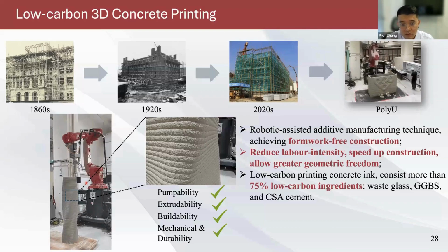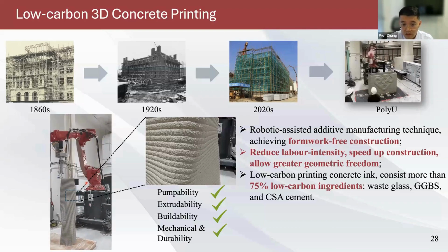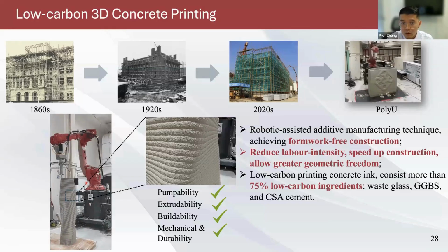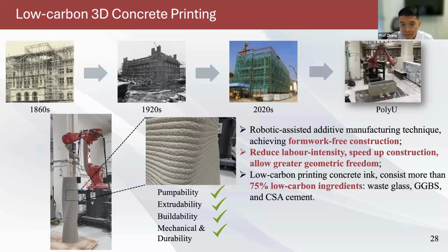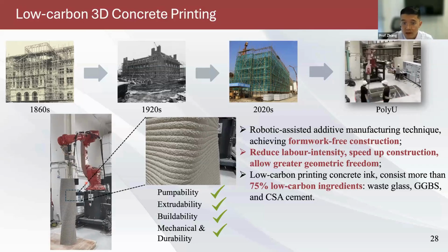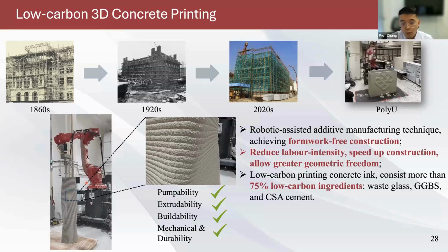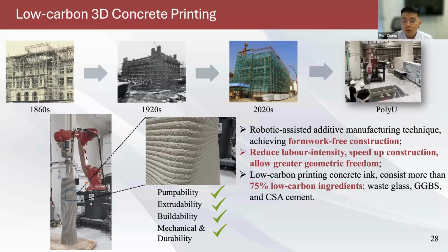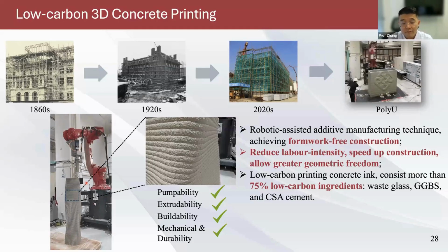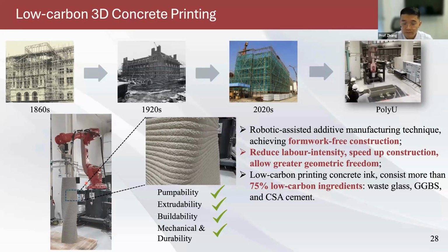But for 3D printed concrete, the extruded concrete itself has to have a very good green strength, so it can hold its own dimension and bear the weight from upper layers without dramatic deformation. The common way to achieve that is to increase the cement content. Normally the cement content in printed concrete is doubled, higher than cast concrete.